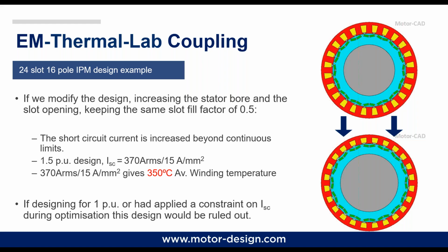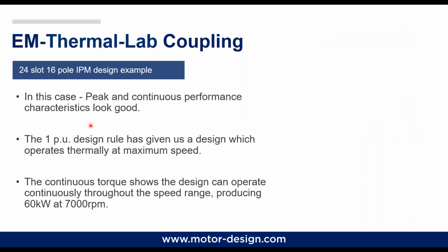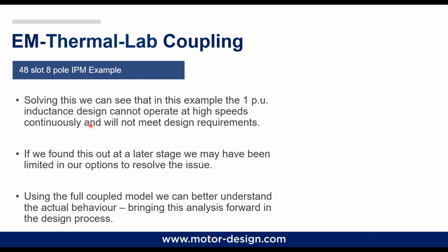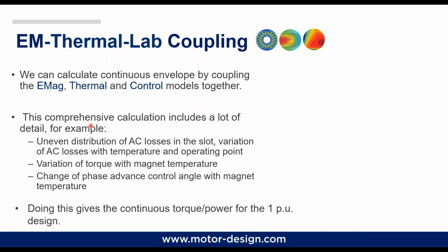So the power of MotorCAD: we don't do basically CFD analysis in MotorCAD, because what we use is a lumped circuit thermal parameter network. We developed this model over pretty much 20 years of Motor Design Limited and MotorCAD. So the idea is, instead of using complex CFD analysis, we figure out a quick way of analyzing an electrical machine based on resistance, capacitance, and so on.